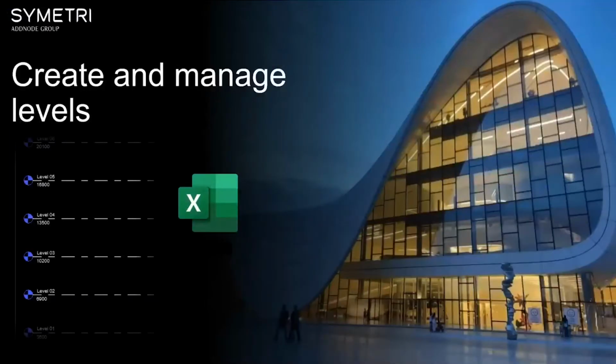Okay, so whilst the creation of levels does not take an enormous amount of time, the management and editing of levels can be very tedious. For example, we may have a 10-story building and need to change the floor-to-floor height just on a couple of levels, perhaps for the plant equipment. This means editing all the existing levels and ensuring that other levels stay at the same floor-to-floor height. This Dynamo script actually comes in two parts. So the first part is going to show us how to actually just generate those levels, and the second part will show us how we can effectively edit those levels.